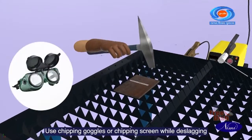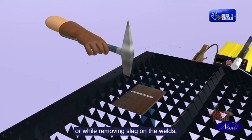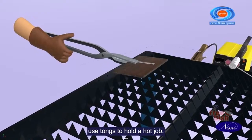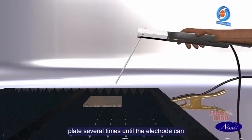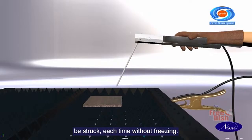Use chipping goggles or chipping screen while deslagging or while removing slag on the welds. If the welded job is small in size, use tongs to hold a hot job. Strike the arc on the scrap MS plate several times until the electrode can be struck each time without freezing.